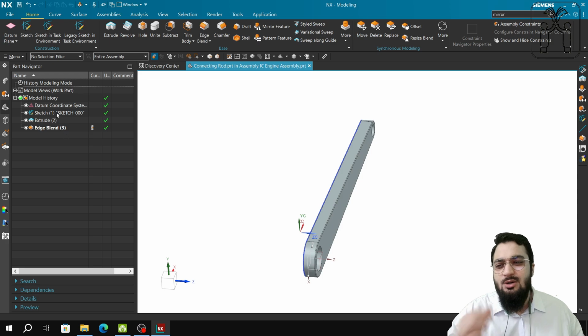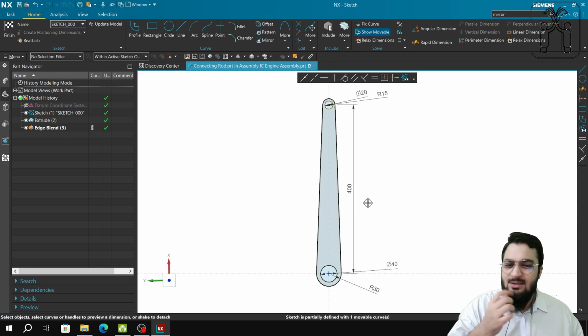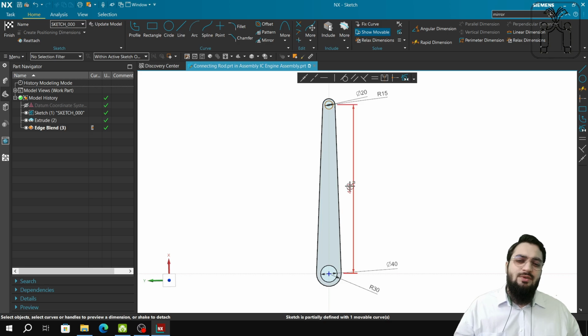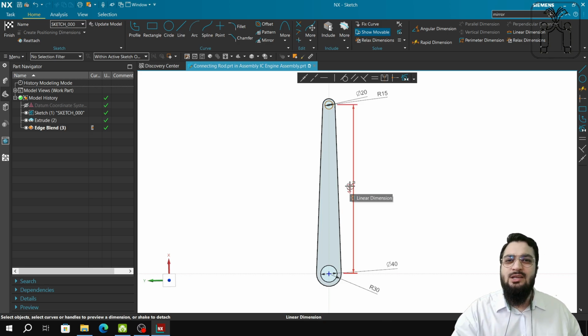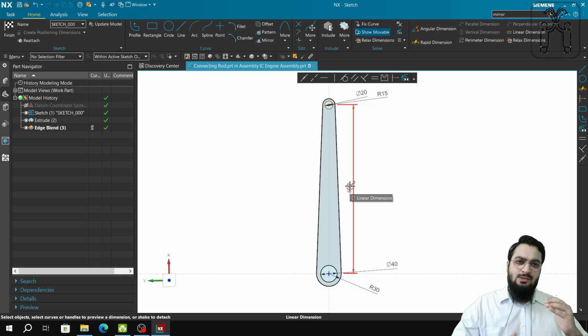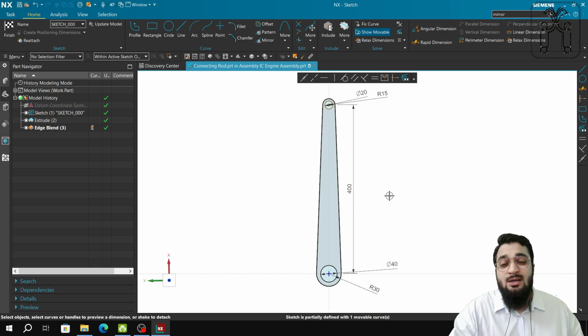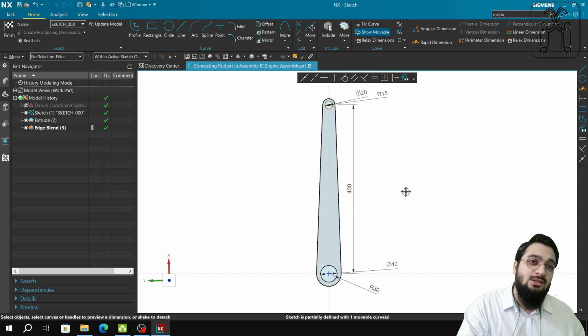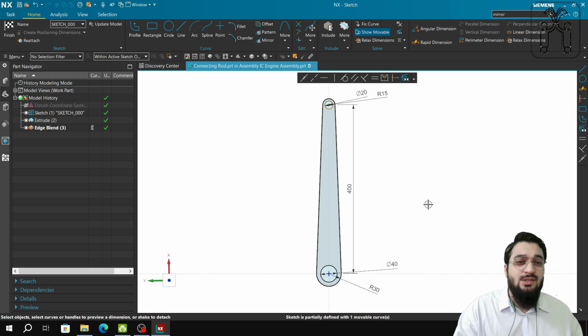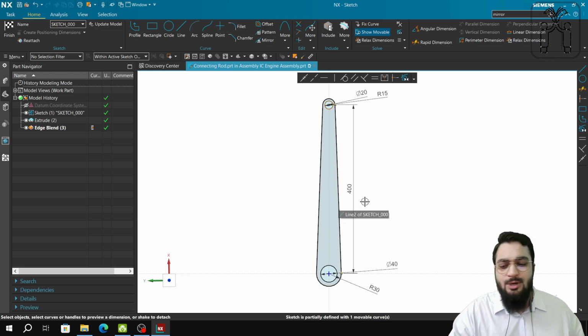Connecting rod is also similar to that of the crank, but the only thing is that it is of slightly more length. So I have taken the length to be 400. It is not like something fixed, you can take as per your own preference. The only thing is that the connecting rod should not touch the cylinder while it is assembled and in motion. And the second thing is that the length should not be too long, resulting in the cylinders and the piston looking very small and insignificant. So it should be something in the middle.